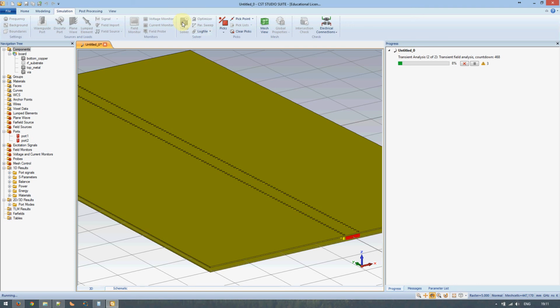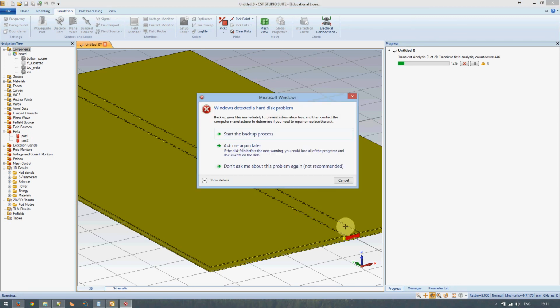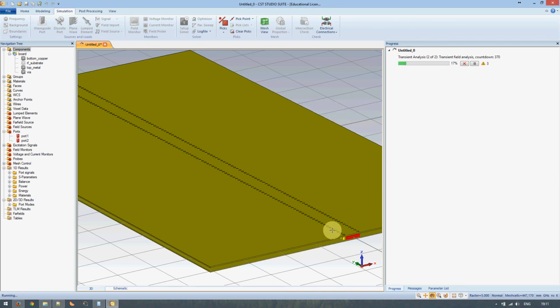So that option that we had, accuracy minus 30 dBs, it waits until the signal in all the cells is 30 dBs lower than the amount of energy that you put in the front in the beginning. And with a cutoff, if you simulate over cutoff, then this stuff just bounces back and forward, and it never reaches that. Well, it does eventually reach that minus 30 dBs, but then your results are wildly wrong.